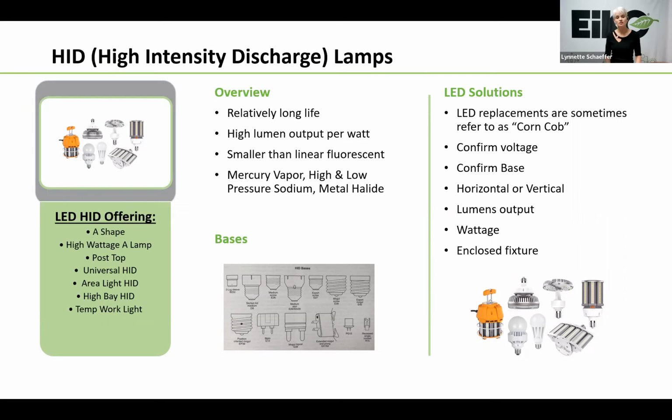Now, since some HID fixtures also use 480 volt, it is very important that you realize that not all LED replacement lamps are suitable for 480 volt operation. That's why it's also important to know, especially in industrial applications and high bay applications, what voltage your customer is currently using. And like many others, you've got to confirm the base. Also a new one, horizontal or vertical operation. Be sure to use the appropriate lamp for the application too.